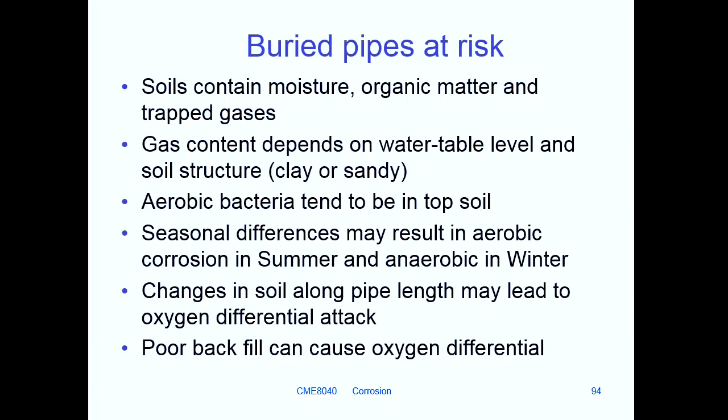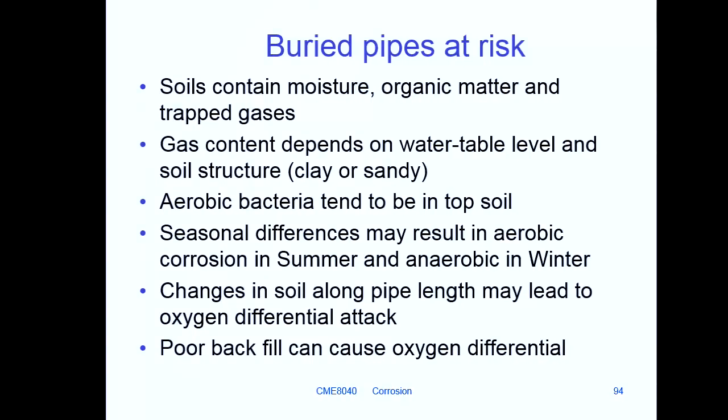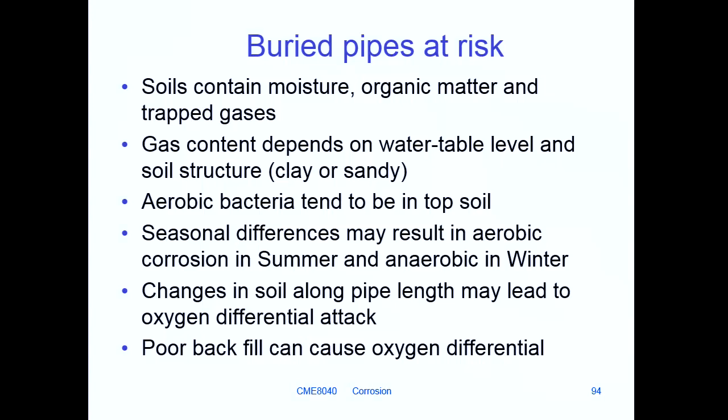This would probably be hyphenated backfill. There's a problem when you bury pipes. It's a common problem. You dig a hole, and what you should really be doing is very carefully putting the topsoil to one side, putting the clay to another side, taking out the boulders, and then putting your pipe in and backfilling.